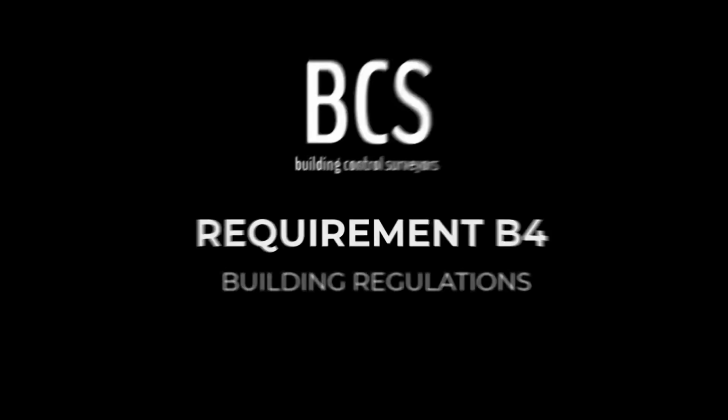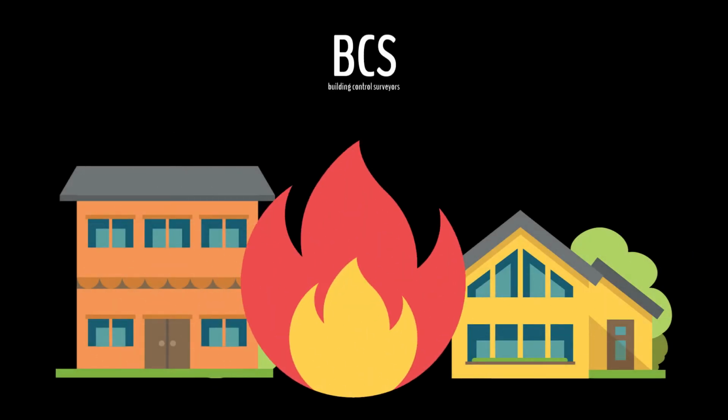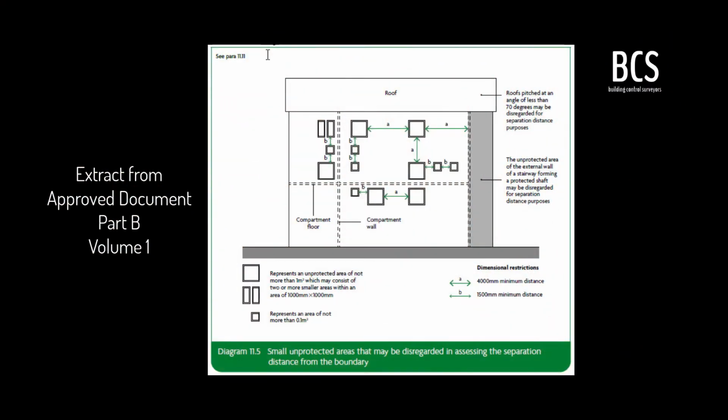This message relates to requirement B4 of the building regulations. The risk of fire spreading from one building to another needs to be considered and the risk reduced, in order to prevent a fire originating in one building becoming a major incident by spreading to other buildings. To reduce this risk, requirement B4 of the building regulations in England and Wales restricts the amount of surface area on the side of a building that does not meet the minimum fire resistance standards.